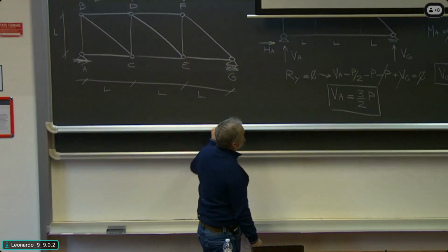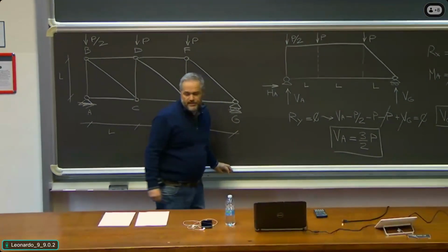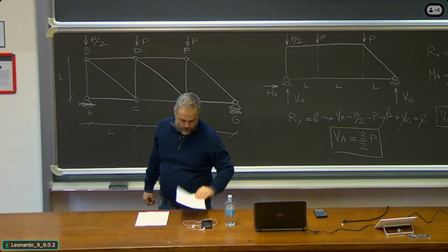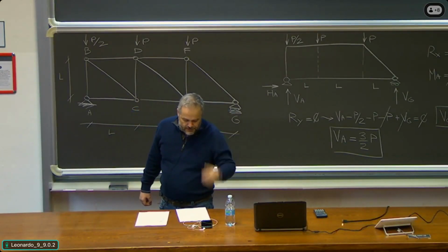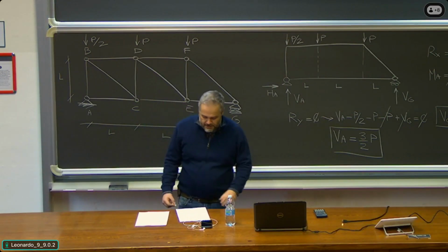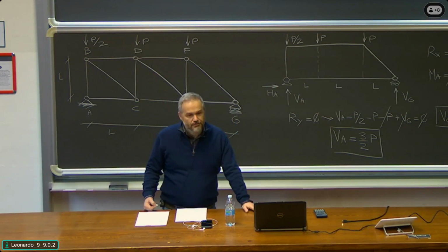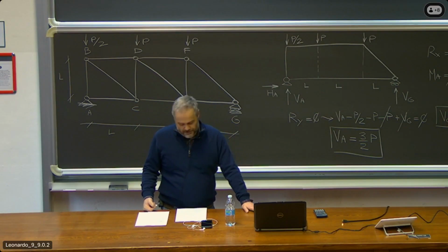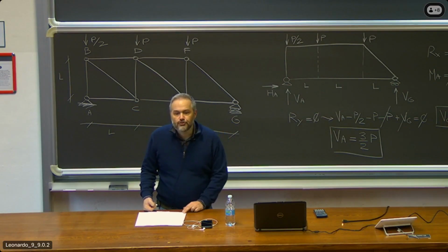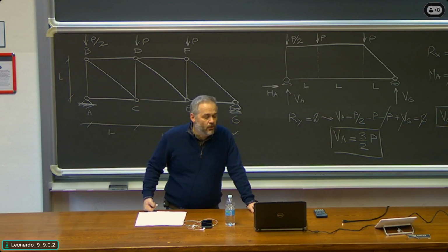Now, we have to go to the second task, which is determine the axial forces in all members by means of either the node or the section method, and clearly indicate the value and sign. And by sign I mean compression equal C, tension equal to T of the axial forces. I am free to choose my method. Since I have to work out all the axial forces, I will go with the node method, okay?